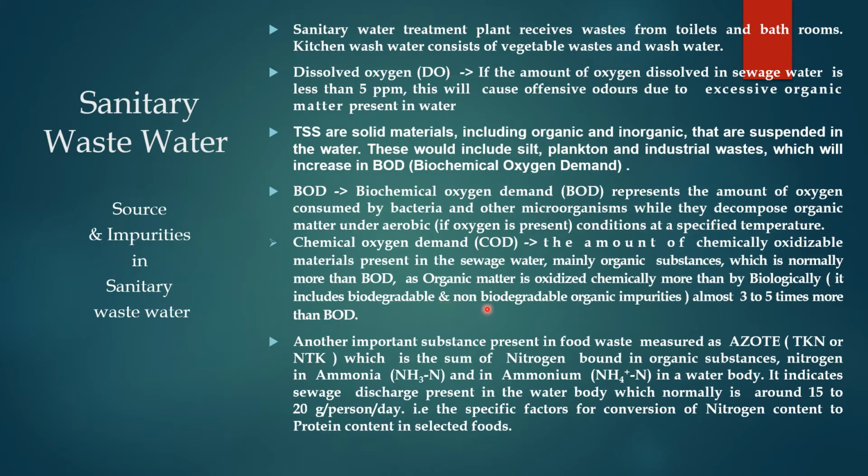It includes biodegradable and non-biodegradable organic impurities. So it is almost 3 to 4 times more than biochemical oxygen demand. So chemical oxygen demand is the oxygen demand which completely oxidizes all the organic material present in the sewage or wastewater.